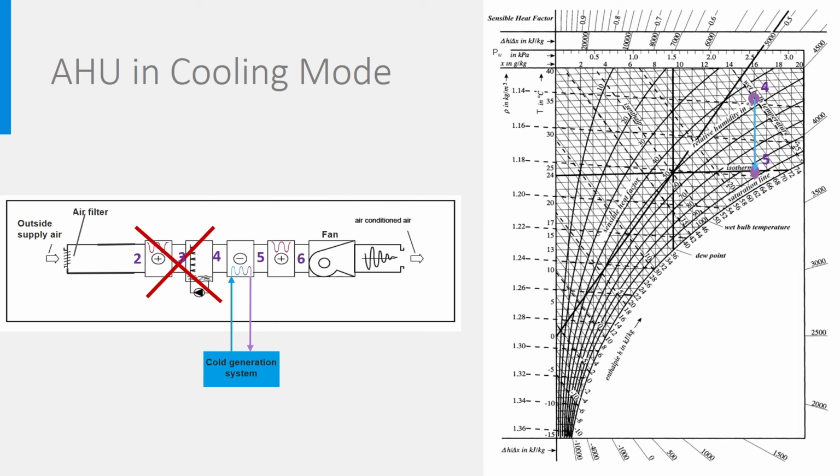To dehumidify the air, a solution is to go on with cooling along the saturation line to the dew point 5, by which the water vapor in air condenses. The air becomes drier and the droplets must be drained away. So, in coolers, there must be a drain. Look on the picture left. At point 5, we have now much too cold air that must be heated to the right temperature using the second heater. This brings us to point 6.